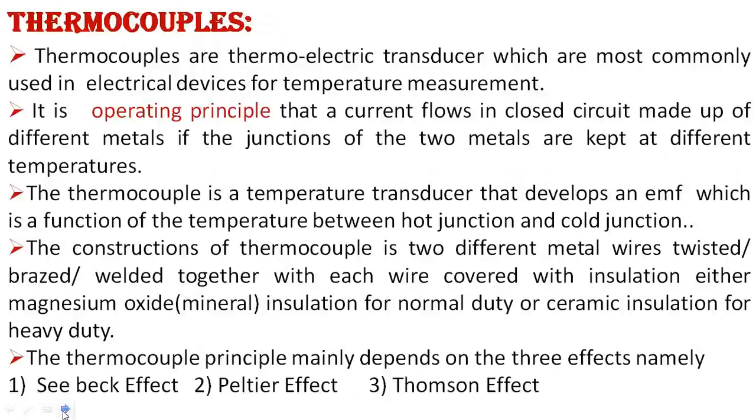Thermocouples are thermoelectric transducers which are most commonly used in electric devices for temperature measurement. Its operating principle is that a current flows in a closed circuit made up of different metals. If the junctions of the two metals are kept at different temperatures, the thermocouple is a temperature transducer that develops an EMF which is a function of the temperature between the hot junction and cold junction.